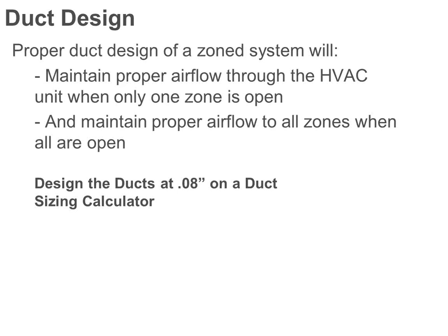So it may end up only being 80 or 90% of the full CFM of the zones. So I may have, for sake of argument, 1,000 CFM for all my zones' peaks, but the peaks aren't all at the same time of day because of the different exposures. So I may only need an 800 CFM furnace, 800 CFM supply duct, feeding 1,000 CFM of branch ducts, right?